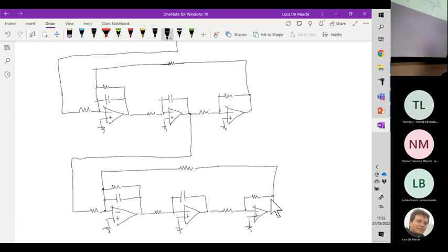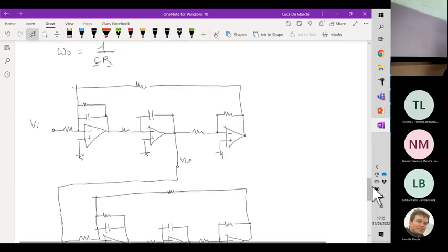Okay. So let's start to plug in some of the circuit parameters. In the first stage, this resistor here is 16.9 kilo. This is 16.9 kilo. This is 35.3 kilo. This is 12 nanofarad.